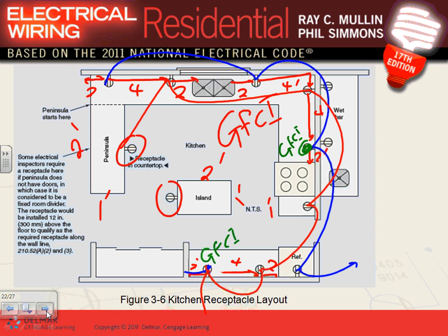The garage by code, you have to have one receptacle for the garage. If you have a general purpose garage, you don't do a shop there, with a 15 amp circuit, honestly, you feed one receptacle general purpose and one for the freezer there, both of them have to be GFCI by code, you're good. But if you are a handyman and you do a lot of work there, it would be nice to throw two circuits there. If I am to wire my garage, I will put more than one receptacle in the garage, definitely. And I will put 20 amps in the garage because I do a lot of work.